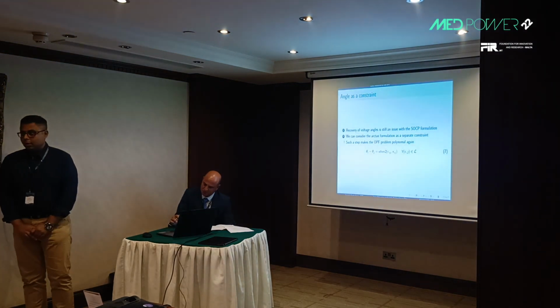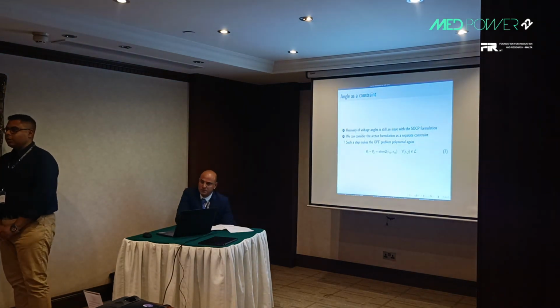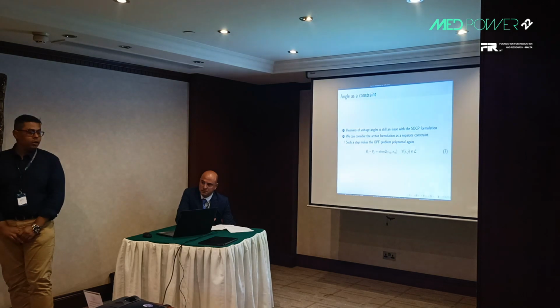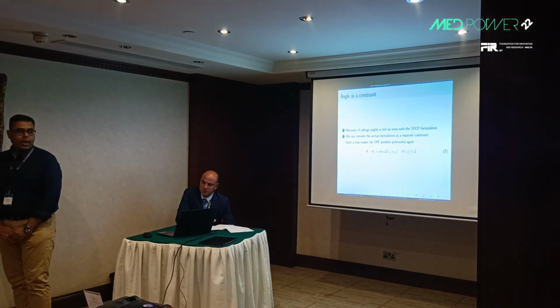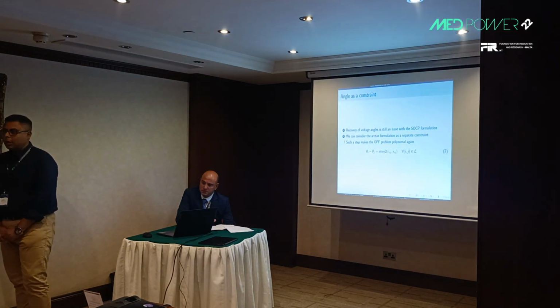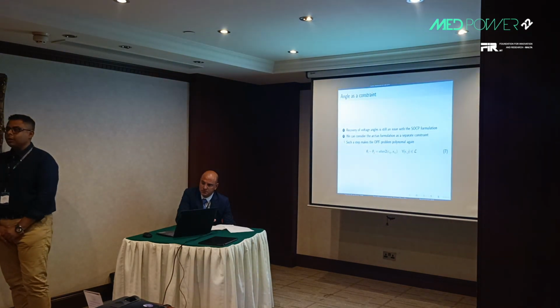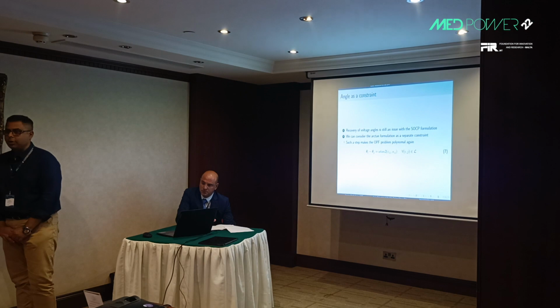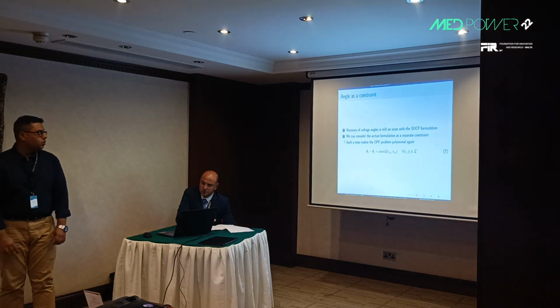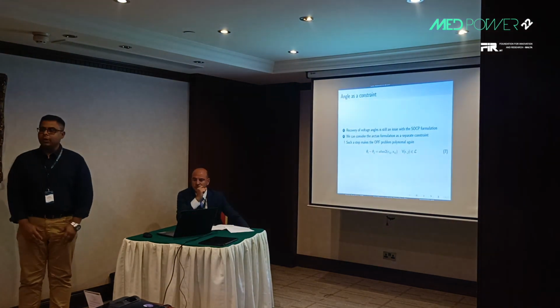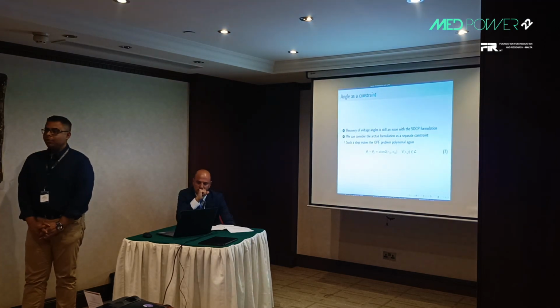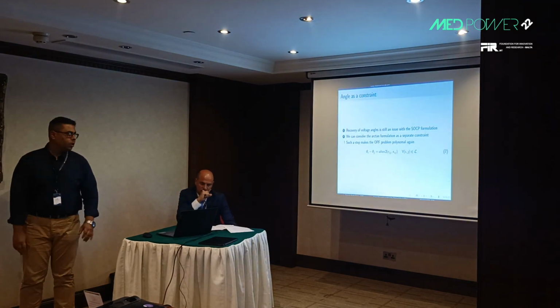But conic relaxation also suffers from angle recovery. So we add the angle-based constraint to have angles within the solution, not as a post-facto solution for the OPF. The only problem with this is that the OPF problem becomes polynomial again.